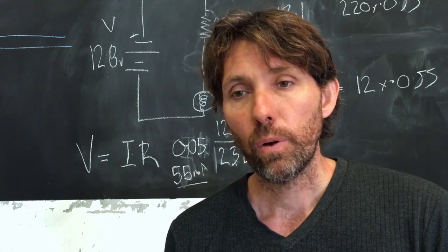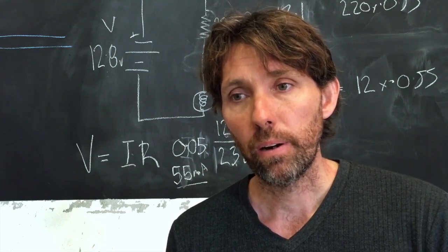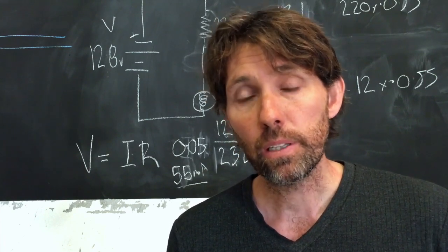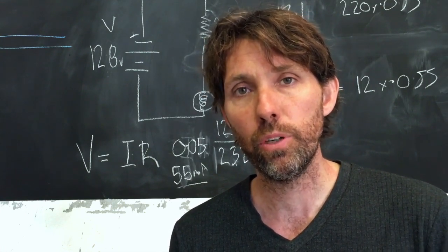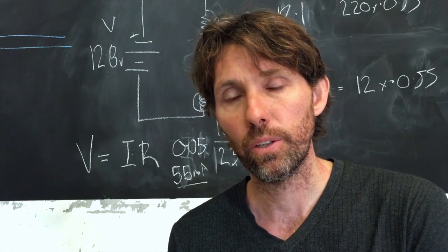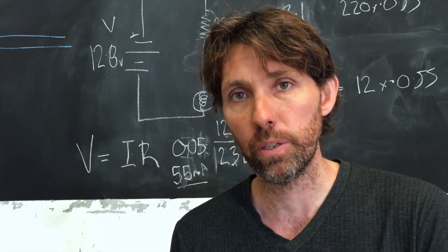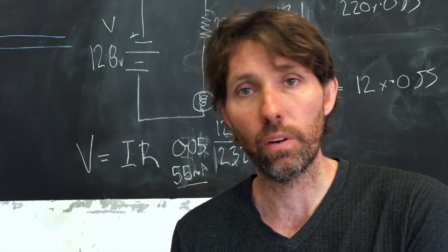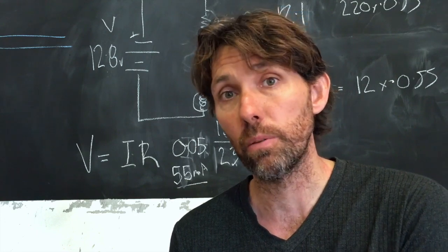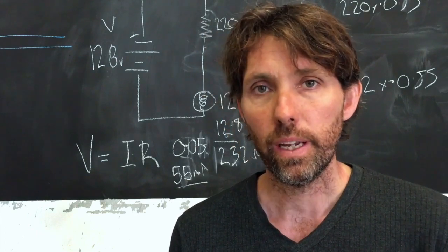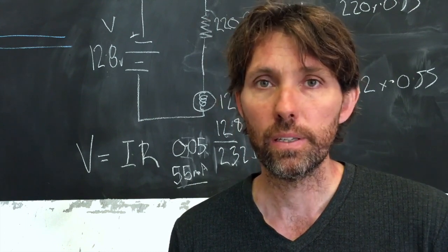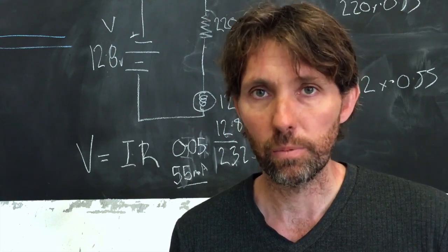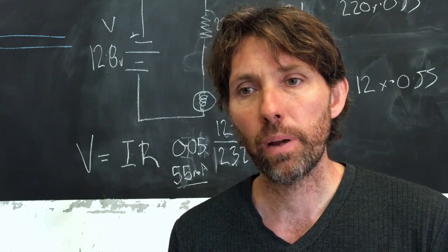If you measure voltage drop, make sure you do it in parallel, i.e. you keep the circuit complete, so the current's flowing through that circuit, and then you just take the two probes and you measure on one side, so the positive terminal of the multimeter, on the side of the device or the section you're measuring closest to the positive terminal of the battery, the negative probe of your multimeter on the other side of the device closest to the negative terminal of the battery. And that way you're measuring in parallel.